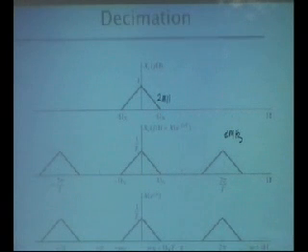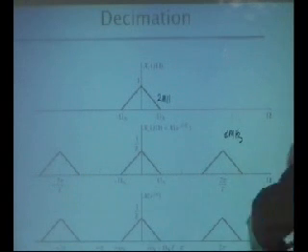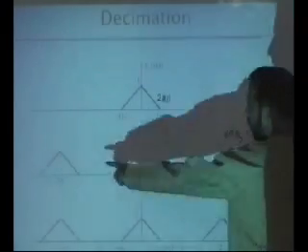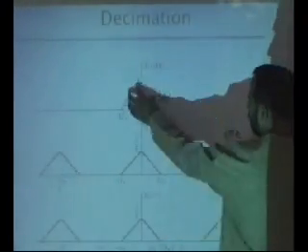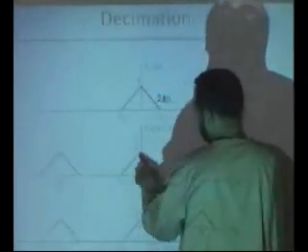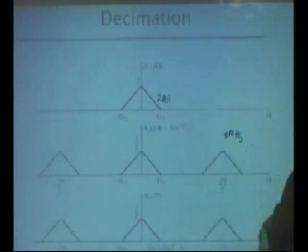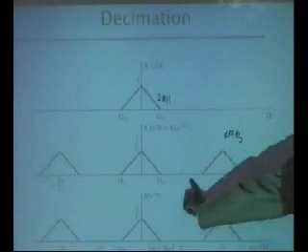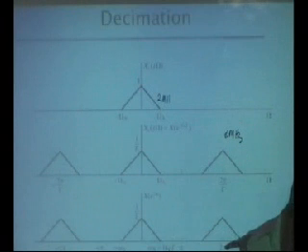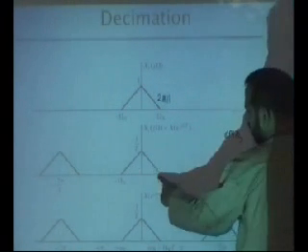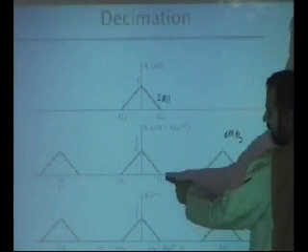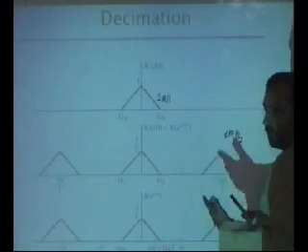For some reason you sample it at 8 megahertz, and you know the process: your sampling rate is 2 pi over capital T, minus 2 pi over capital T, making copies of this here, and this is 1 over T. Then you change it to digital, this multiplied by T, so you get this at 2 pi, this at pi, and this will be at pi by 2.